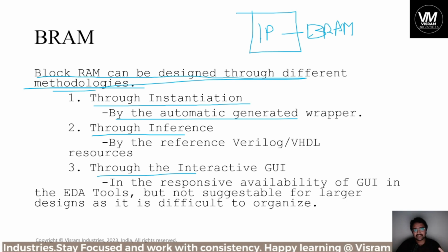We utilized the EDA tool from Xilinx, took the IP integrator and clicked the button for generating the Verilog HDL wrapper. Then we simulated a test bench and tested it by debugging the errors. That is how you have to check the Verilog HDL generated by the machine. Usually it doesn't make mistakes, and 99% of the time it is good. But for the 1%, it shouldn't ruin our hardware circuit.